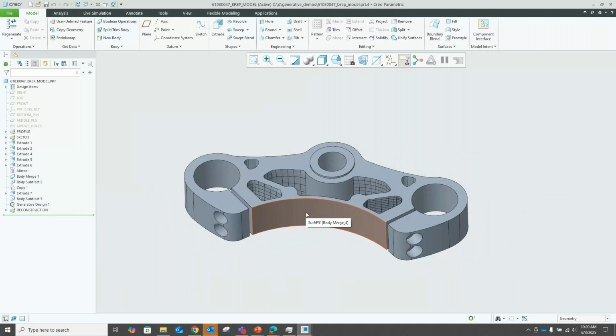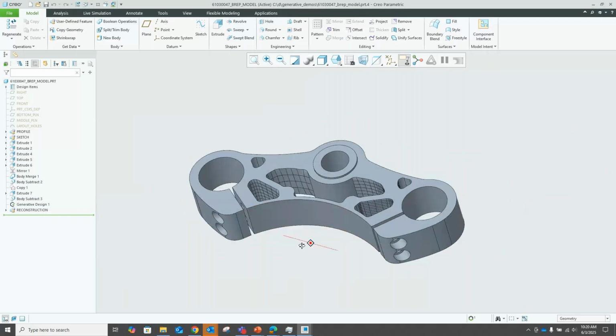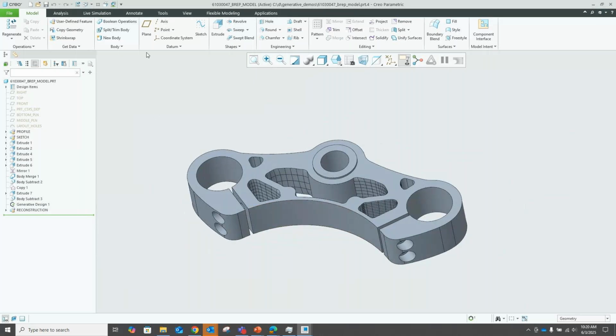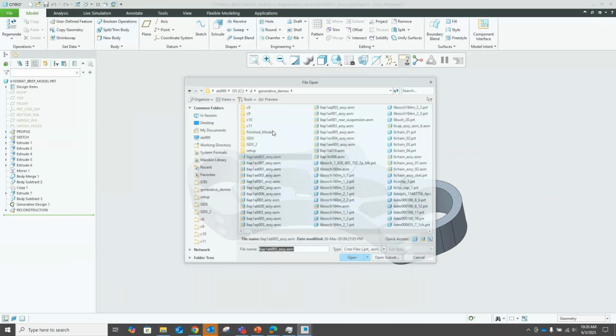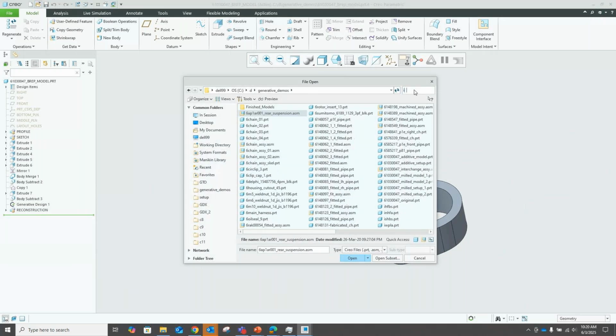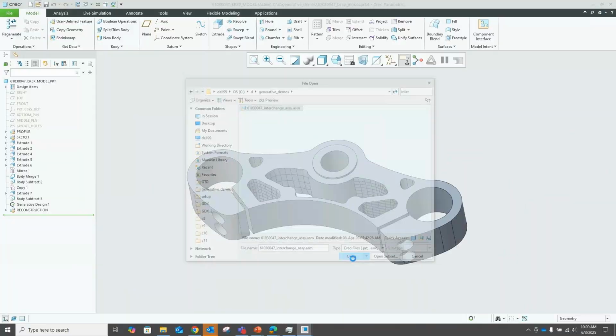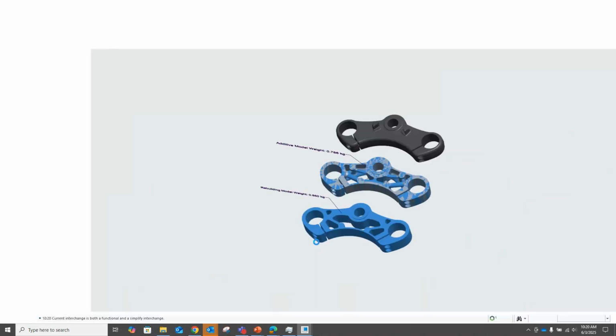compared to the initial one. And so there could be several variations like these with different materials, different load conditions, etc. Right? Or I should be able to go and even create an interchange assembly where I could use my different variants. An interchange assembly is essentially a bucket for all your variants, right? That some of you may have used.